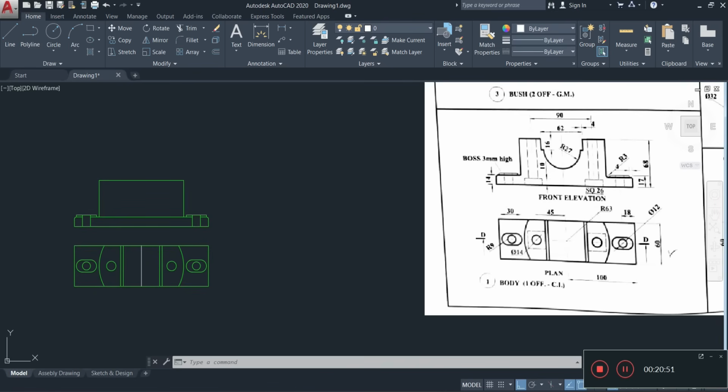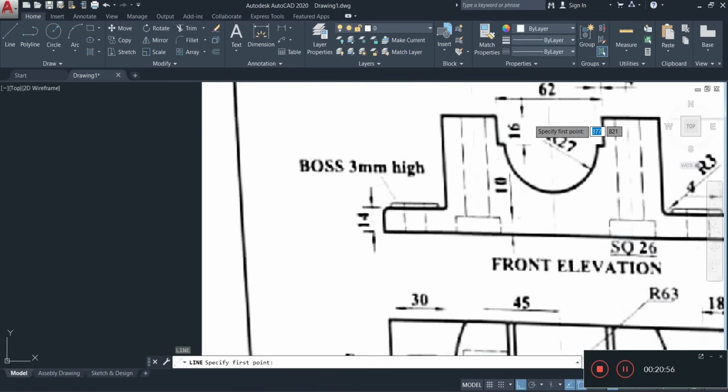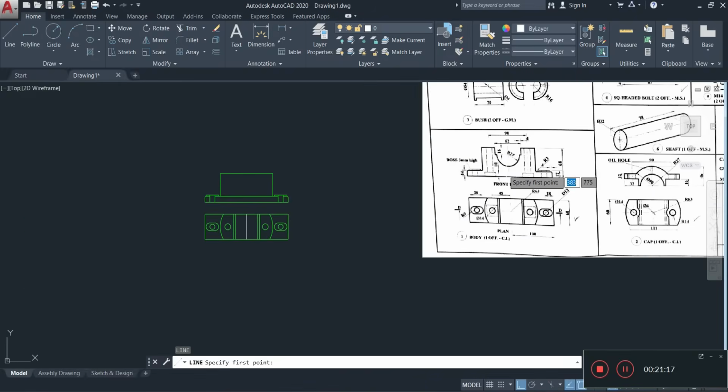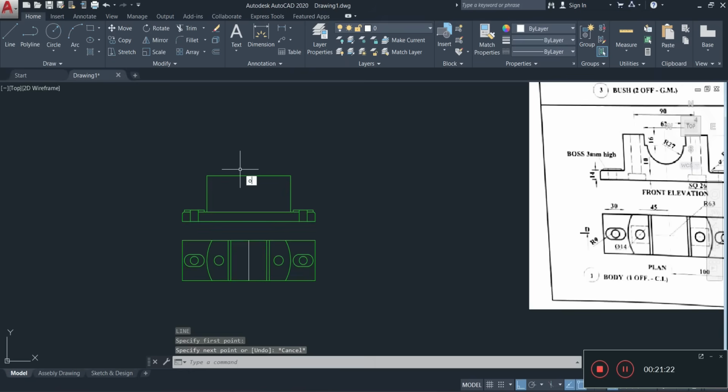Now, the curvature portion starts, so you can see what's going on. As you can see, it starts about here and it goes down, the radius being 27. From the top down to here, this locking portion here, the measurement is actually 16. So we're going to start things off with that. We're going to offset down 16 from that point. So offsetting 16, let's go. O, enter, 16, and let's offset that down.